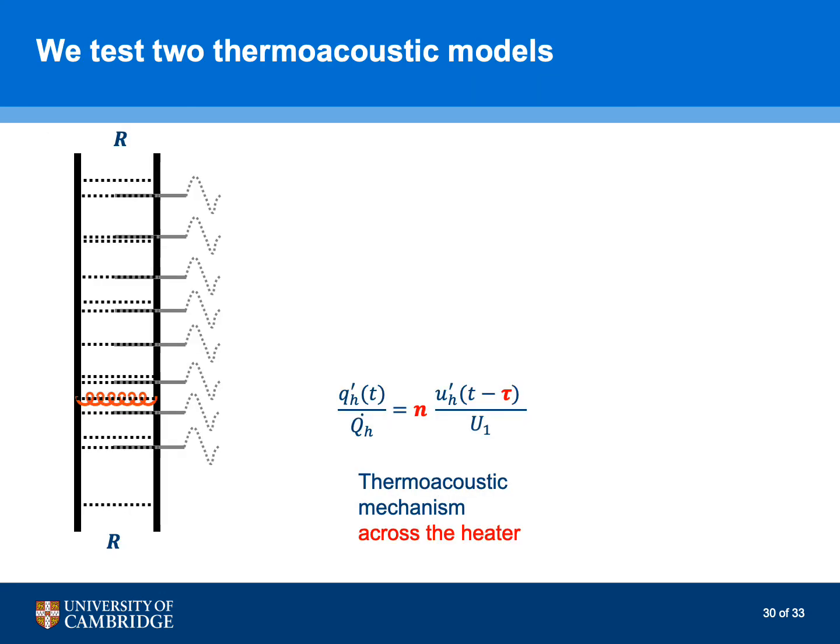The last step for us consists of modeling the thermoacoustic effect that occurs when we switch on the heater. For this, we need to know the speed of sound in each acoustic element as well as the inlet flow speed, computed in the first part of this work using the ensemble Kalman filter.